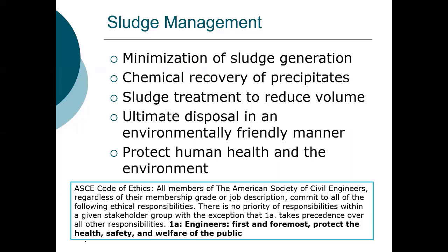We want to reduce the volume of the sludges, so we're going to treat it. And we mentioned that we need to reduce the volume. Why? You can make the processes later on smaller sizes. Okay, so we want smaller sized processes if we have to do any subsequent treatment. And why else?